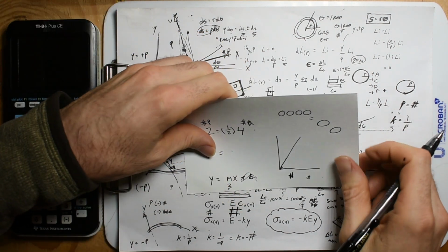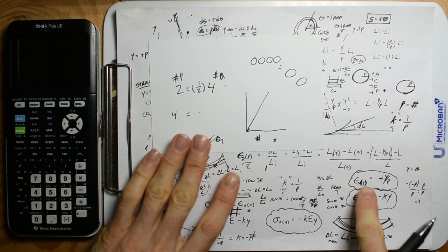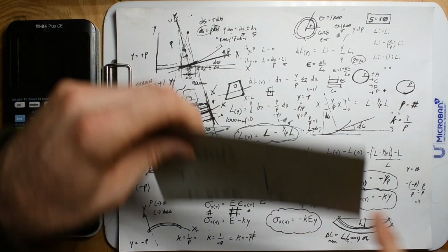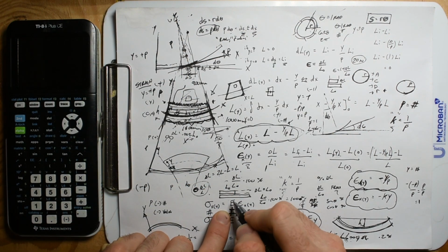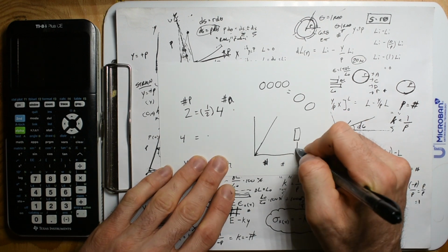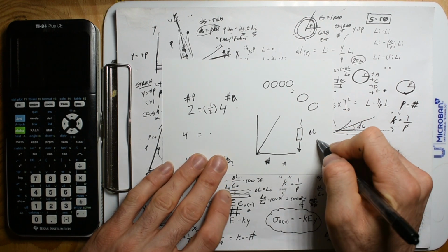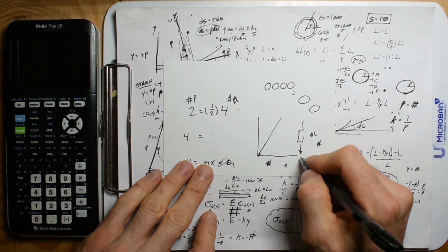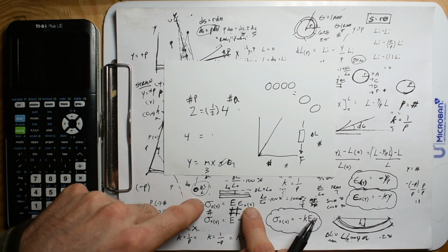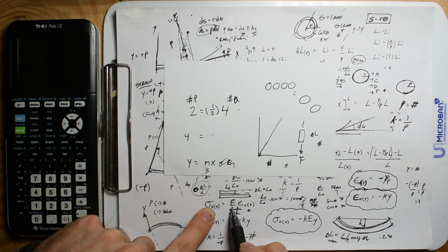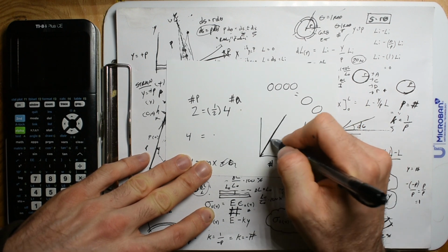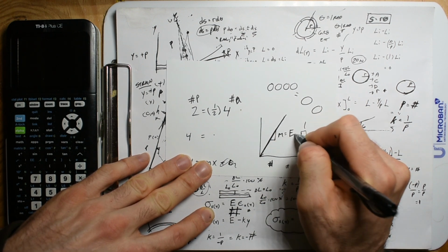All right. So now we solve for this strain equation, and we're just plugging it into here. This elasticity is a constant. So this is where we take some steel, pull on it, see its change in length. We can get that value for strain, and we can know how much load we put on it. Change in length and force. That's kind of what you're doing here. And then you're trying to get an equation that relates change in length and force, and we see a linear relationship. So our slope is just E. You know what I mean?